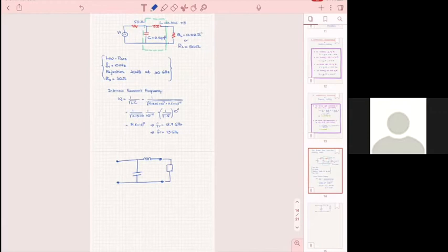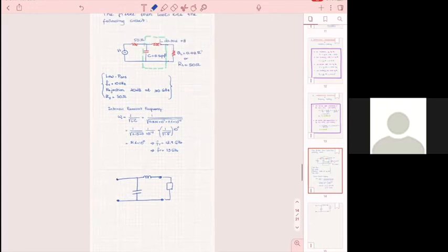I believe the f sub R is not correct, because it's 81.6 times 10 to the 10th radians per second. Oh, 10 to the 9th, excuse me. Yeah, 10 to the 10th. Then it should be 129 gigahertz. Let me see, you divide by 2 pi. Then it should be higher. Yes, you're right. Let me check it once more. He's right. I mean, Zehin is right.